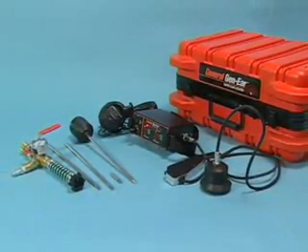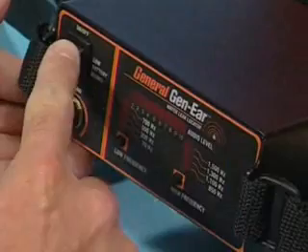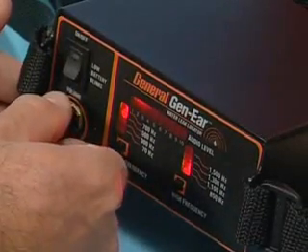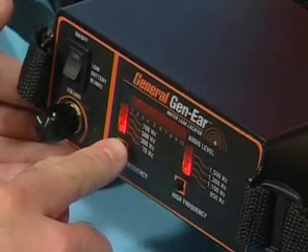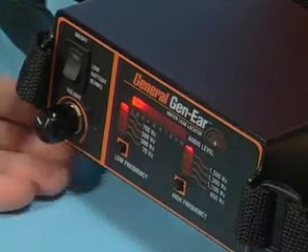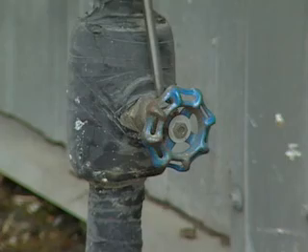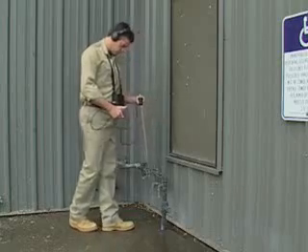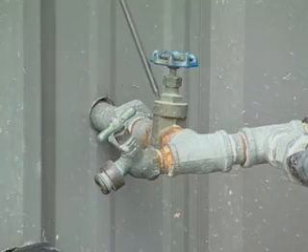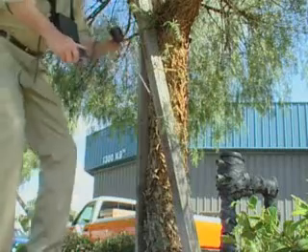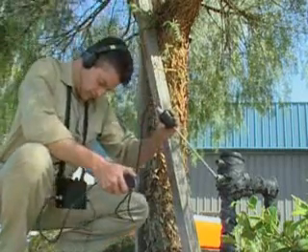To conduct a water leak survey, start by setting the filters to 700 Hz low and 1500 Hz high. This is the most common leak sound frequency. Make direct contact with the probe sensor and the probe bar to all sink lines, hot water heater lines, hose bibs, hydrants, and main valves. This gives you a general location of the leak.